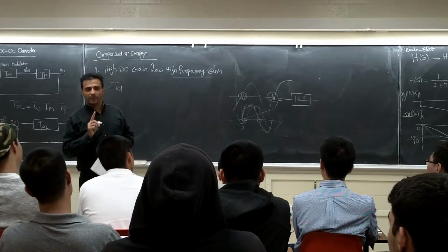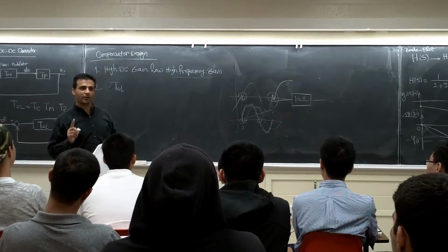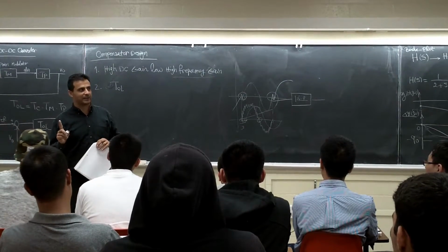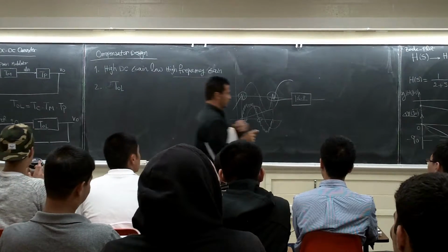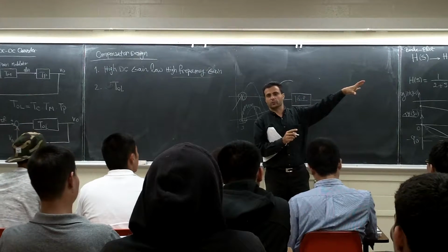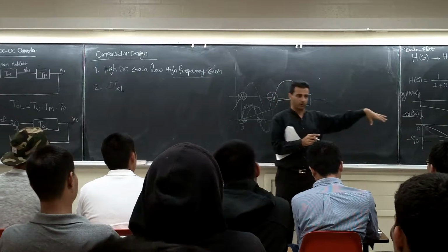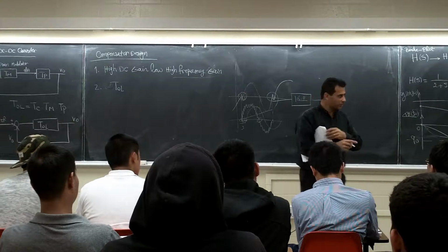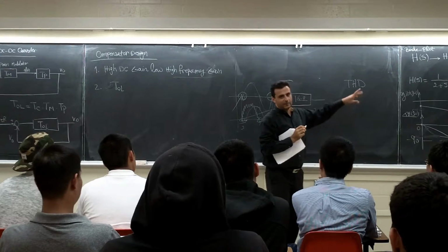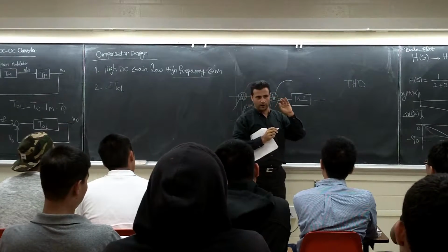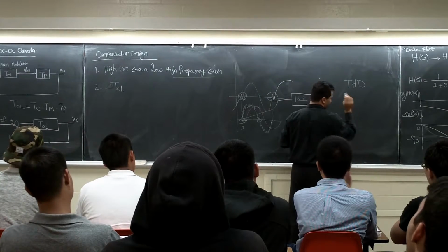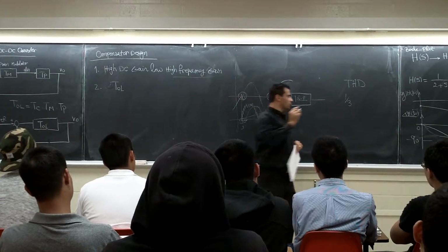For example, the CEC standard. There are lots of rules around here, they're not going to let you do whatever you want. CEC has a THD profile. I want to finish this thing, I'm talking too much. When you design a solar converter, let's say a 5 kilowatt converter, you know about THD, total harmonic distortion for the current. They have a very strict rule, but I'll tell you a very simple one. It says at 1/3 of the rated power, you should still be less than 5%.